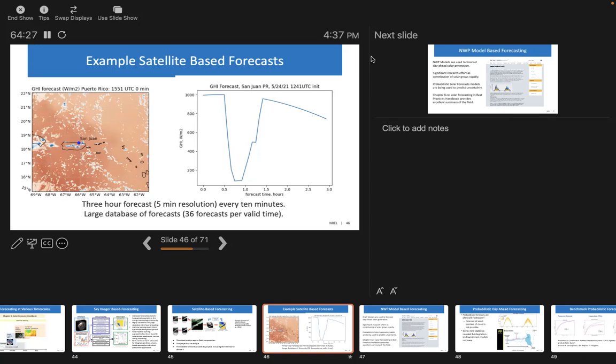But the data from the satellite, if you want to build something like this, you have the NSRDB, I told you. You can take that NSRDB data, which has all the information at 5 minutes, and you could essentially derive this forecast in hindcast mode. You build your technology, but the data is available. So you build the forecast. The advantage is you can also validate after, because you have 1 year of data. You build your thing, and then you have the next 3 hours of data available to check if it's working or not.